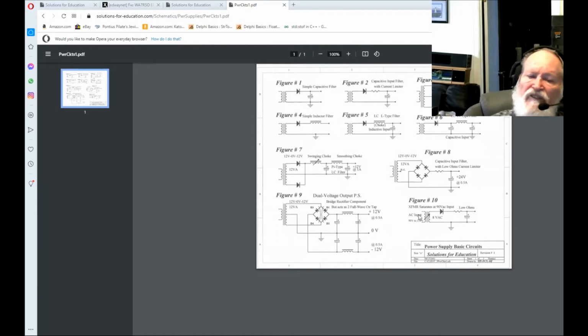You say, okay, fine, I'm not on the mission field, I have no use for this. And the answer is, wait a minute. Back in the early days of computers, before the ones we're using right now, when the S100 systems were around, they all used TTL circuits. TTL circuits are critical for voltage. You go below 4.5 volts, they don't work right. You go above 5.5 volts, they don't work right. You want 5 volts, so you set up a power supply system with all the regulators to give you a nice 5 volts.